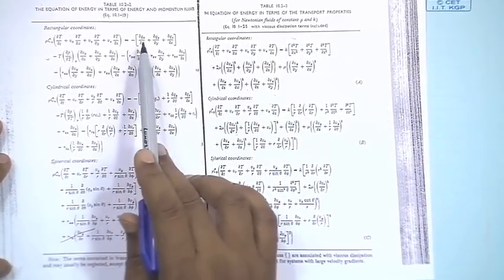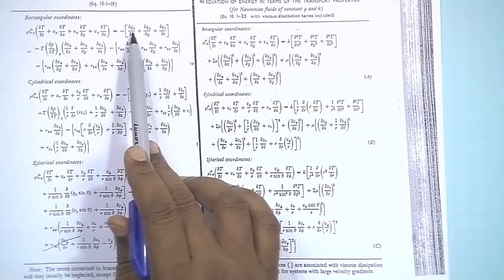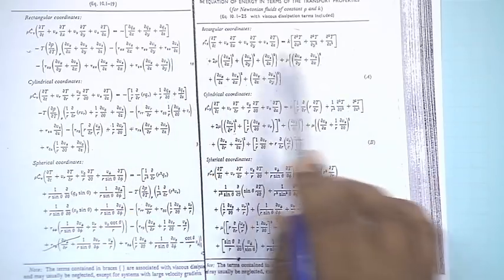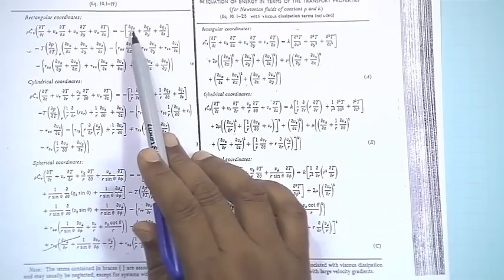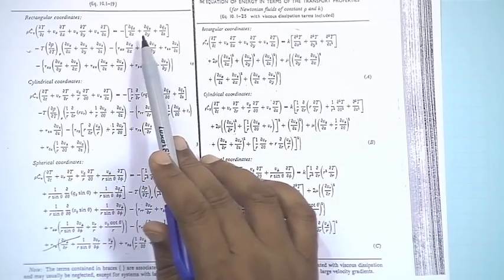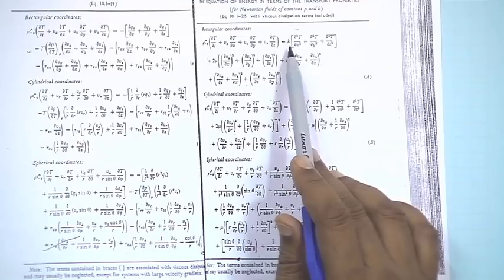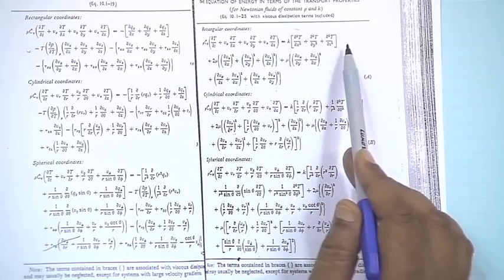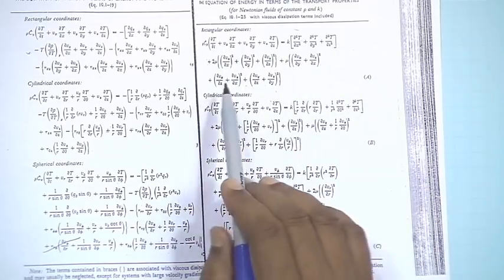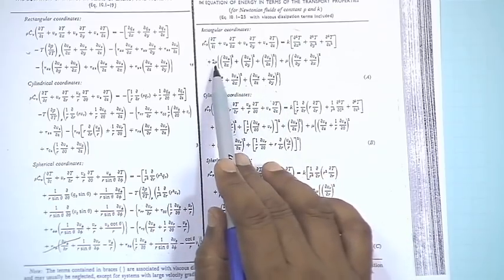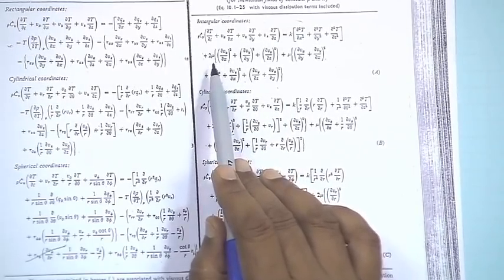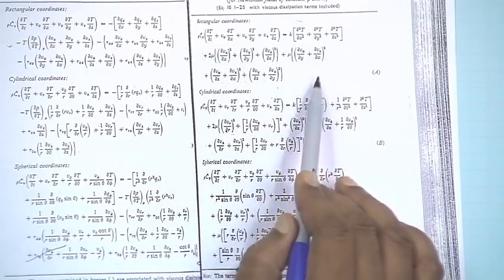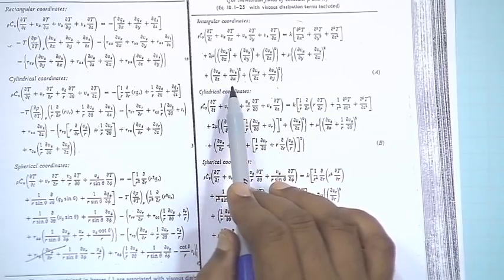The first column refers to energy, the conductive heat in the form of qx, qy and qz in rectangular coordinates, whereas on the right hand side of the table, the Fourier's law has been substituted in here, and if we assume the thermal conductivity K to be independent of position, then this would be the form of the equation of energy for a rectangular coordinate system. Notice this entire term with viscosity mu in front of it. So, if you have viscosity, this term refers to the viscous heat generation, or in other words the function phi that I have introduced before.